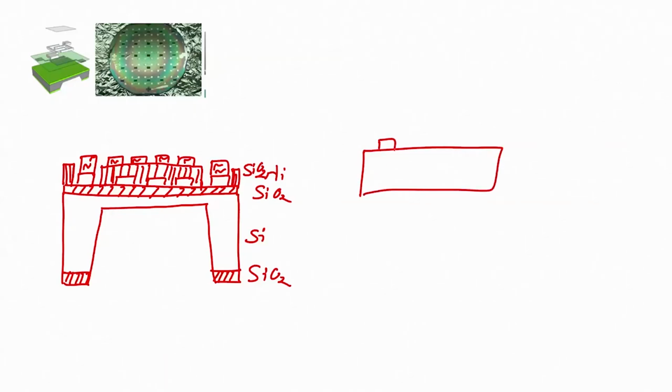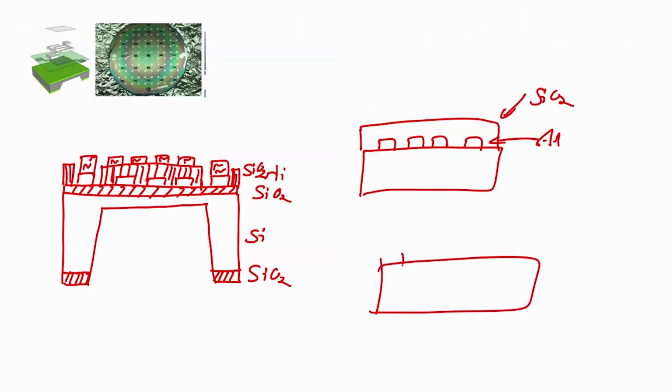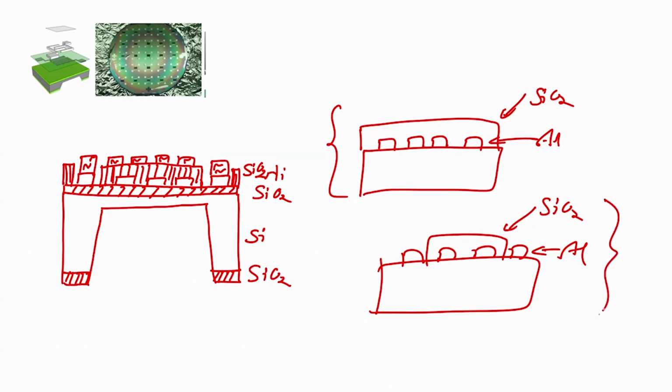Suppose I say that I have a wafer with aluminum, right, and I have SiO2 which I want to etch in a way that it should look like aluminum is here and SiO2 only stands here. Okay, you got it, right. If I have this wafer with SiO2 covered on aluminum interdigital electrodes and I want a wafer which should look like this, which is my aluminum, and SiO2 should only cover these two parts of the design. So, I have to perform lithography, right, and finally, I have to dip this wafer in BHF, correct.